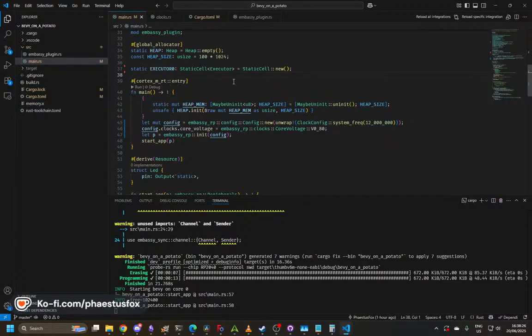Busy. I don't know if Busy's actually going to connect to anything. We then have reset. Again, I don't know if reset's actually going to end up connected to anything. We'll have to find out when we pull in the driver, because half the time these drivers don't connect half the pins, because they're not normally needed. Okay, DC. We're also certainly going to need DC. So let's plug DC, and then we're going to go Pico pin out.